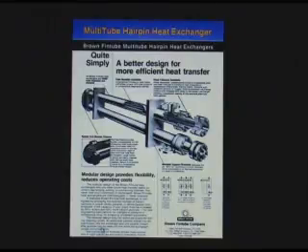They're very good. Brown Fin Tube manufactures them. RW Holland manufactures them. We have had issues with both suppliers, though, that the nozzle loads from our external piping coming into these units has needed to be looked at very closely because of the limitations of these closures.